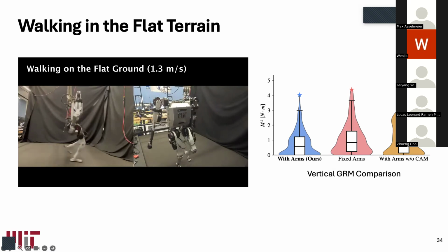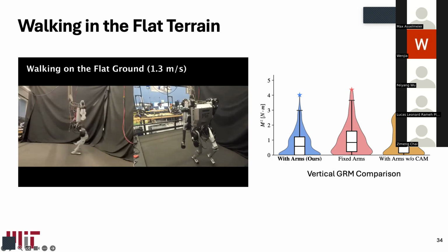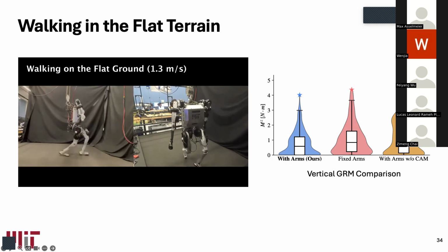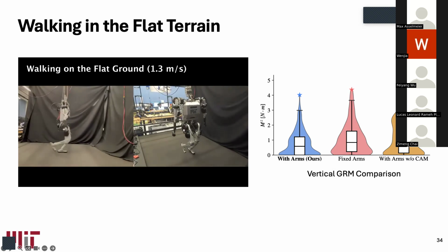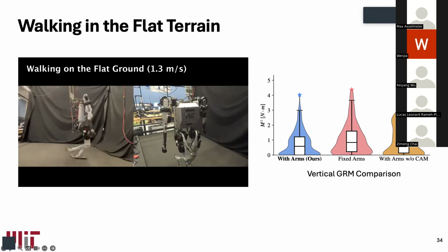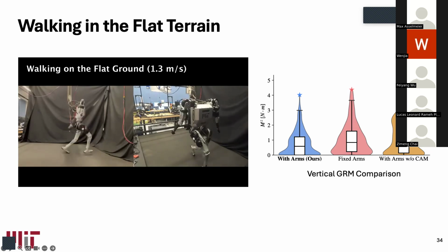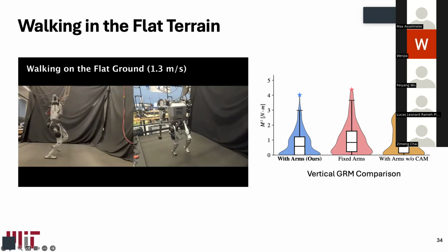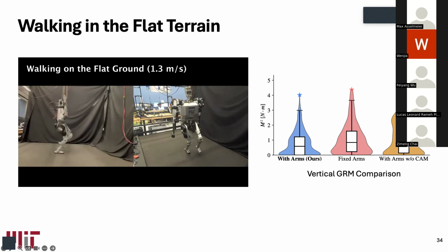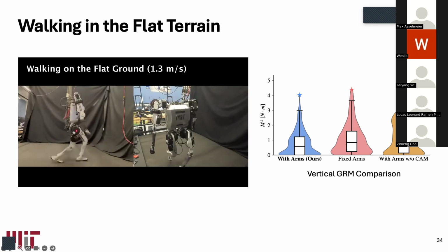Yes. What if you lose the joint regulation term? Joint regulation, reward for your arm a little bit, then would it? Yes. So that comes down to like a tuning part. So in extreme case, if you remove the joint regularization term, as Hwan said, it goes really crazy and it's jittery a lot. So we had to tune it in a reasonable range, but not dominating. Yes. Okay. Thanks for the questions.